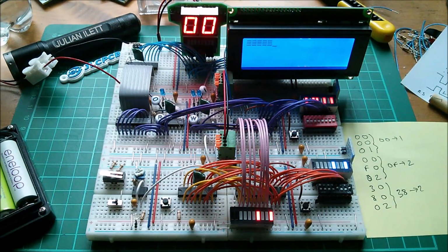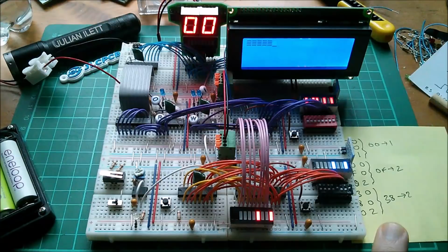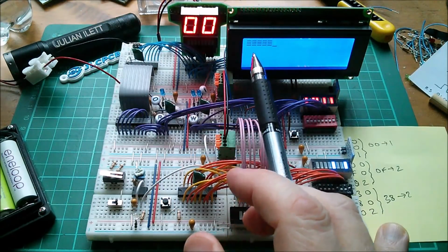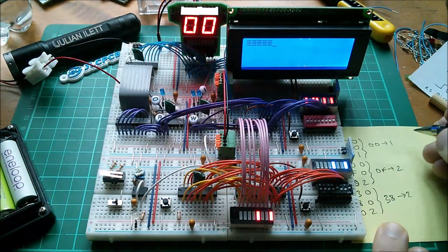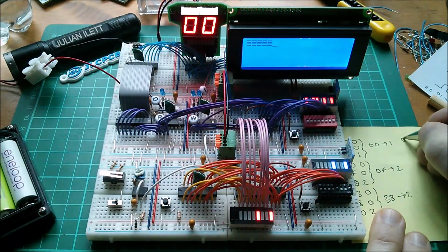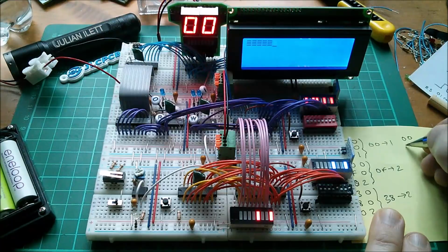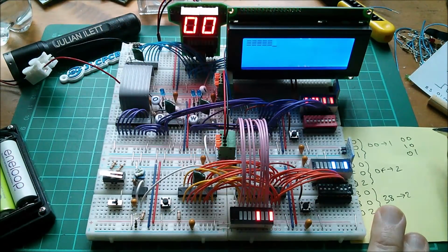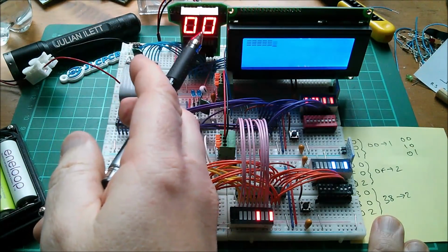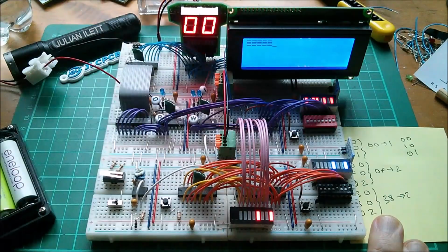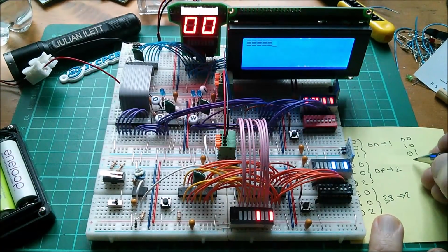So far, so good. So the next part of the program, to write some legible characters onto here, means putting a 0, 1, so 0 to 0, 1 to 0, 0 to 1. That puts 0, 1 into device 1, so that will then say 0, 1. That takes the RS line high. Then we'll need to put a couple of characters on. Well, let's have AB, for example.